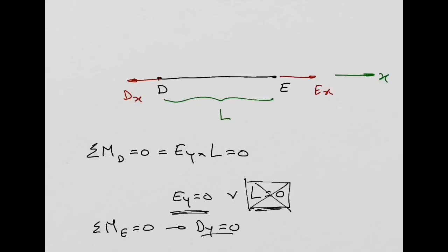So we have these two forces, Dx and Ex. Look at this now. The summation of forces in the x direction equal to 0 is another equilibrium equation for the forces, right? Which forces do I have in this strut in the x direction? I have Ex positive and minus Dx. They need to be equal to 0, right, to be in equilibrium.